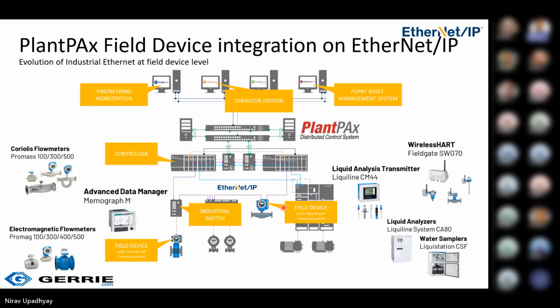Any questions over this architecture? Yeah, we have another question. So we can read the HART data in the PLC. Do we read it in the controller tags? The HART data, once it gets incorporated into the IO tree, automatically gets incorporated into the controller tags, which can be accessed through the logic, correct? Yeah, that's correct. Typically, we run third-party software on a PC to configure the device. That's a good question, Yusuf. Maybe if you can hang on till after the end, we can get deeper into the situation you're talking about, and we'll give it the attention it needs, if that's all right.